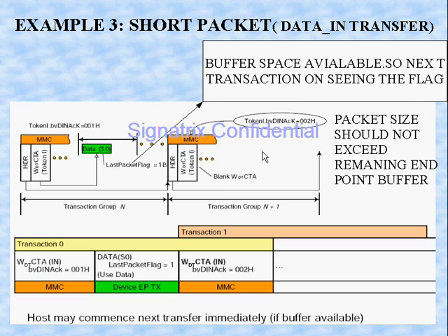In which direction is our data moving in this diagram, towards left or towards right? Which MMC will be received first? This one, and after that the data will come. So it's moving towards left. If you consider it from the device point of view, the device will receive this MMC first, then it has to respond with its data. Next, after some duration, device will receive this.